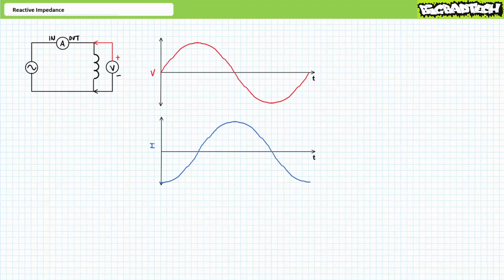During the storage phase, the oppositional voltage spike initially chokes current, and during the release phase, the voltage spike momentarily continues to push current in the same direction. As with capacitors, the problem in identifying the present state of an inductor in an AC system is that the polarity in AC systems cyclically oscillates at a frequency too fast to allow a technician to change the leads of an ammeter or voltmeter to adequately reflect the actual state and polarity of the inductor. Additionally, inductors might seem to suffer from a causality paradox, which I hope to resolve in a moment.